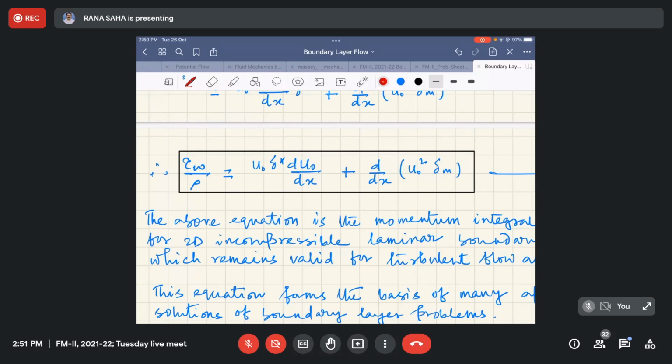In the same analogy, for a flat plate, if it is a straight and parallel plate, I mean, or you can say if it is not changing its gradient, the plate orientation, so we can say that U naught is not changing. So here actually U naught does not mean always it will remain constant. It is basically the velocity where your effect of boundary layer is minimal.